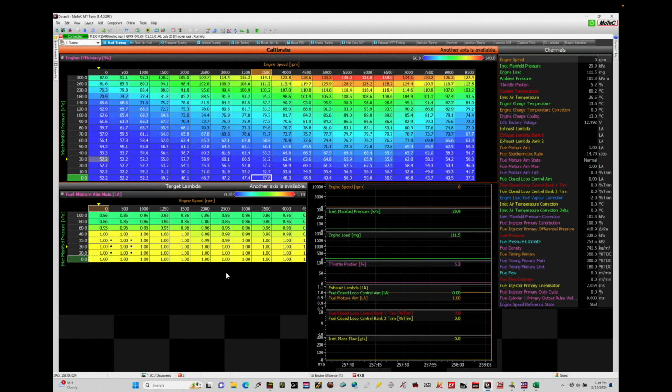Okay, so let's get started. We're going to be taking a look at understanding our engine charge temperature calculations and how it plays an important role in our engine load calculation, which is going to be our air mass determination for the Motec M1 programming. This is really important that we understand the influence from the inlet air temp sensor reading as well as our coolant temp sensor reading, because these both play a role in our engine charge temp calculation.